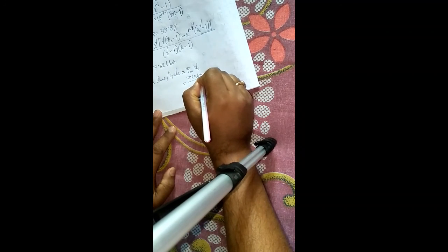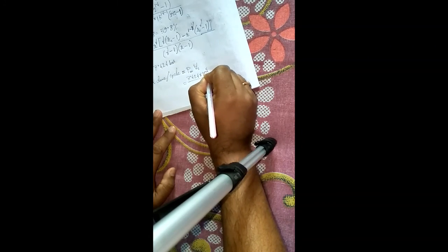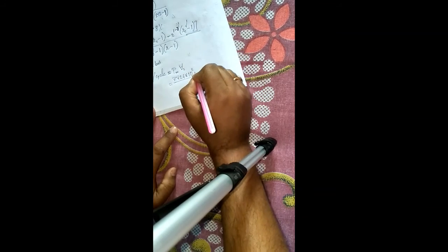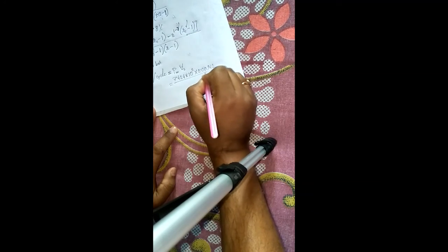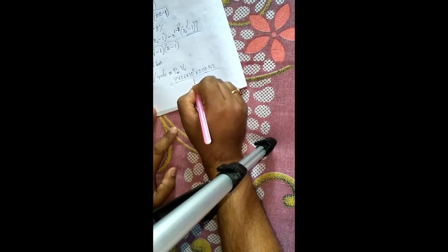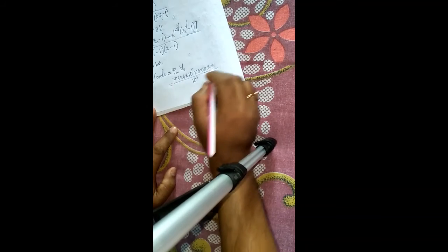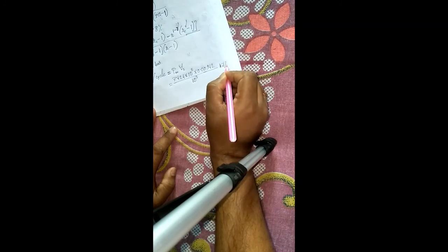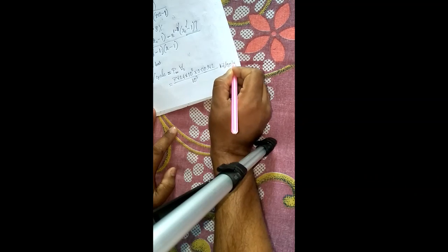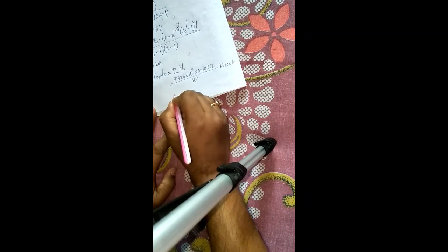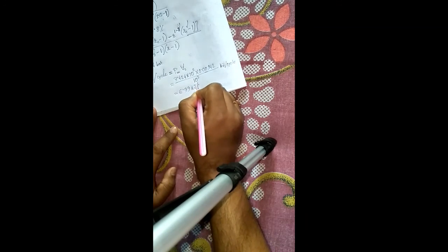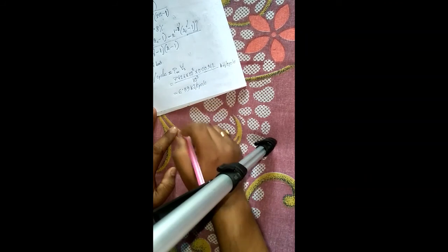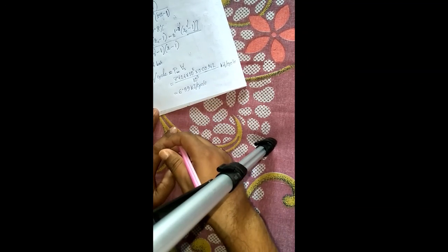Let's convert it into Newton per meter square, that means multiplying it by 10 to the power 5, into the stroke volume, that is 0.00942, divided by 10 to the power 3, that is kilojoule per cycle. So the value becomes 6.99 kilojoule per cycle.